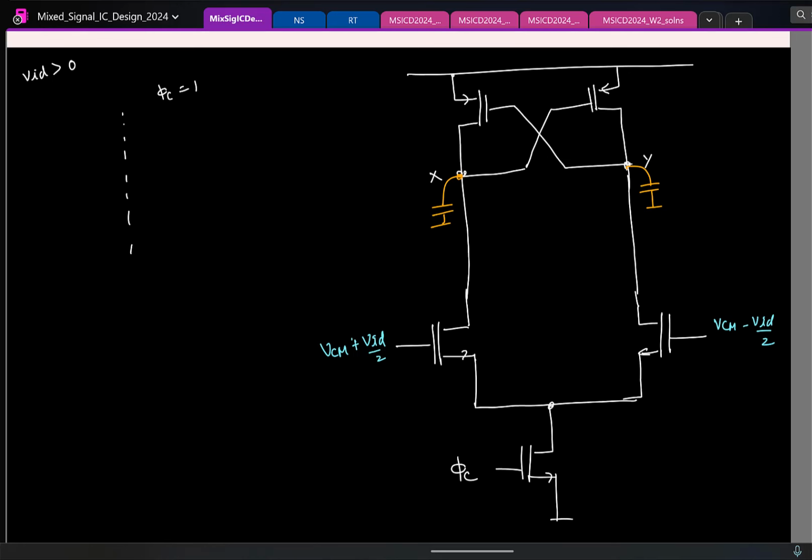So here let us say when the comparator was not active, both the outputs were equal. Now I have activated the comparator. So I am applying inputs here. The transistor will take the input, convert it to a current. So I will have currents flowing in both branches. Which of the currents will be greater? I1? Fine. So I am drawing currents out of this capacitor.